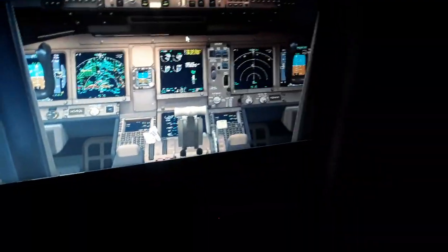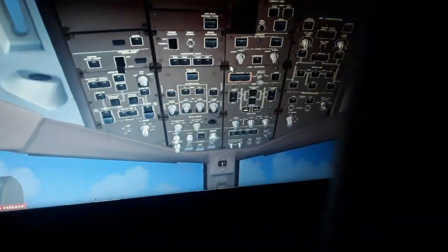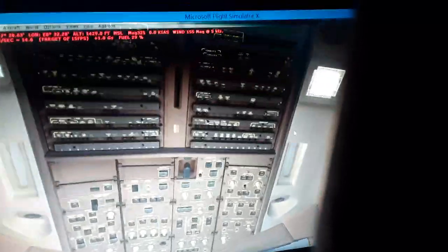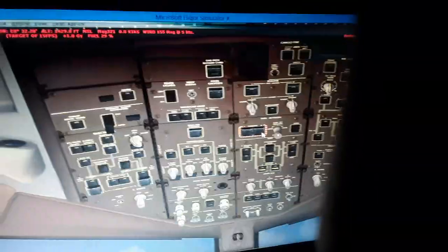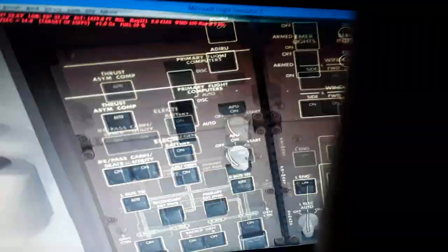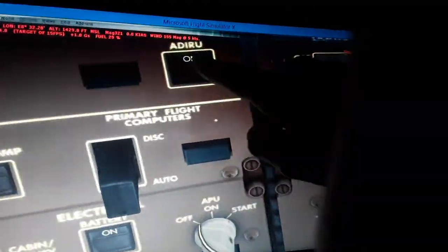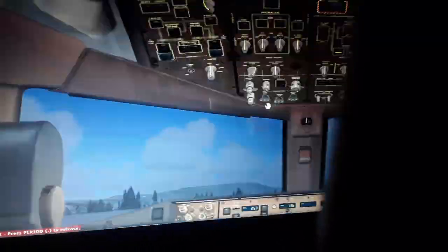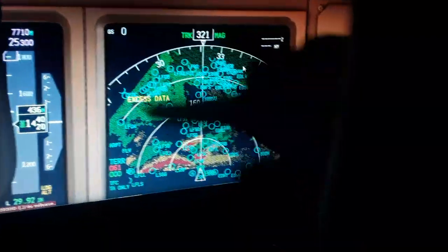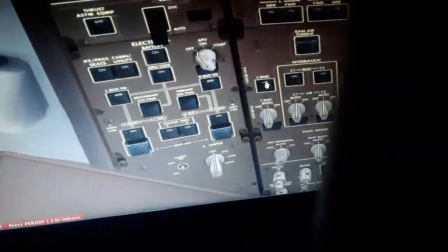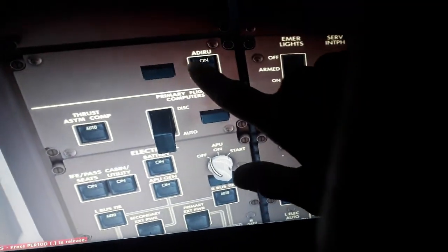The landing gear. So now we'll come in the overhead panel. You can see here is disconnect for fluid from the flight controls. Here is the circuit breakers of the electrical system. I will explain in another slide. We have here the ADIRU, the air data and inertial reference unit that controls and displays all the air data and the GPS position, the gyroscopic acceleration and deceleration, the airspeed, the altitude, all this using the ADIRU over here.